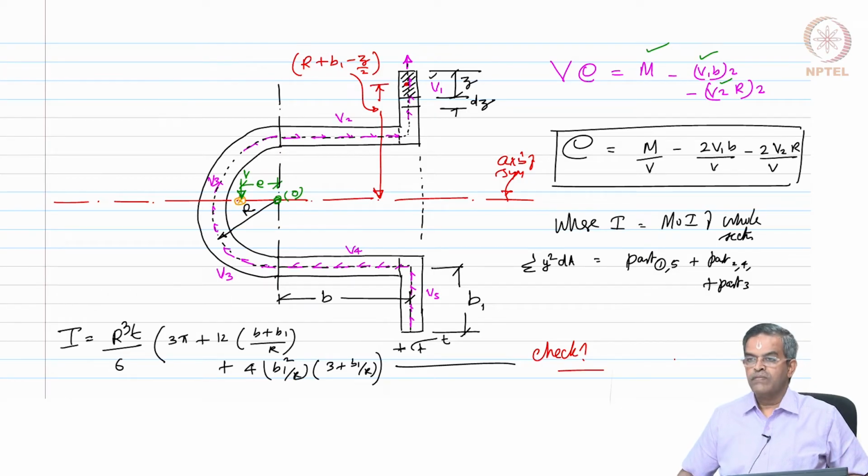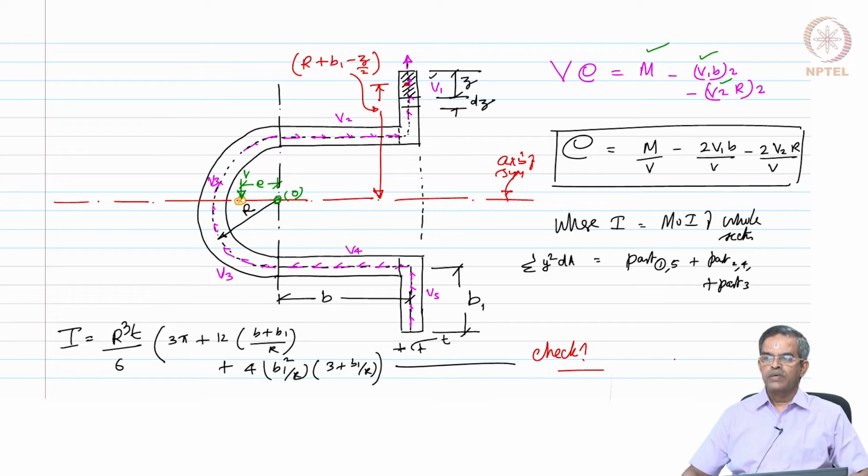So, friends, we have learnt how to do the shear center problem for curved section which has got a mixture of rectilinear and curvilinear sections. From the first principles we found out how to locate e. So, locating shear center for geometrically complicated section is not that easy, okay. We have got to gradually divide them into parts, into finite elements and keep on assembling them and do it slowly and patiently. It is not that easy.